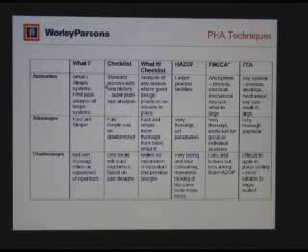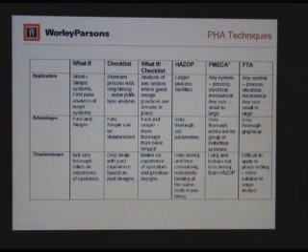And the checklist can be used for a standard process with a long history, so people have a good knowledge of how the system runs and what may happen, what needs to be taken care of. And it is fast and simple, and it can be standardized. The disadvantage is that it only deals with past experience based on past designs. So if we have new designs and new changes, it's not a very good way to identify hazards.